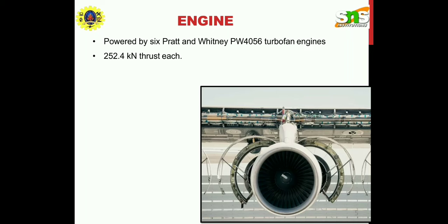Most turbo machines use a combination of impulse and reaction in their design, often with impulse and reaction parts on the same blade. The following dimensionless ratios are often used for the characterization of fluid machines. They allow a comparison of flow machines with different dimensions and boundary conditions. These are the pressure number, flow coefficient, power number, run number, and diameter number.